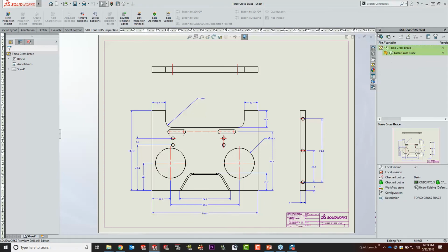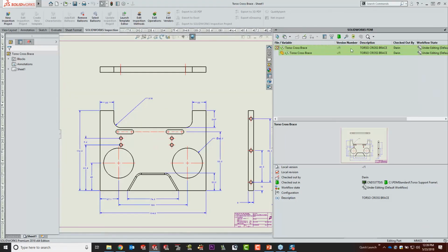Now, with the change assimilated, I can hit save locally, and then that will save over the local cache versions, which now shows in my tree that my local versions are now newer than the last time these files were checked into the Vault. Now, I can change all day long and keep hitting save. The only time I actually create a new historical version is when I take these files and check them in. I'm not going to do that just yet.